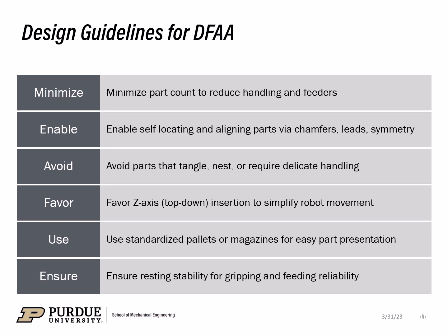You should always review part proposals with the following questions in mind. Can this part be fed reliably? Can it be inserted with simple tooling? And could two parts be combined into one? Are orientation or compliance challenges likely to add cost? These are all very important automated assembly manufacturing questions to ask yourself at the beginning of the design phase, to really pinpoint the difference between manual assembly and automated assembly, and the cost trade-off, and whether it's actually going to be beneficial to your product.